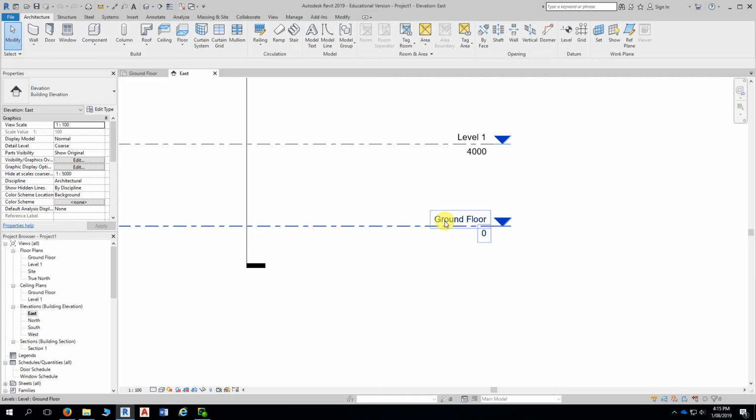And when we draw, we are drawing at ground floor at level 0, at 0 here. So when we produce walls, when we actually draw walls, they automatically have a height and a thickness, okay? So it's not like AutoCAD where you actually draw single lines and offset. The walls themselves are fully complete in terms of their construction.